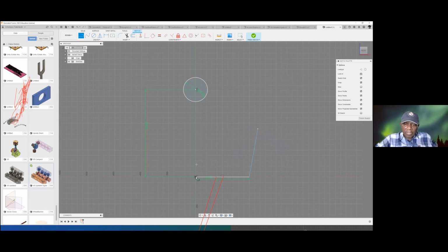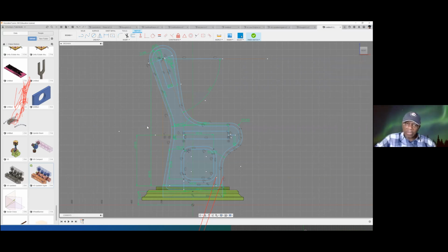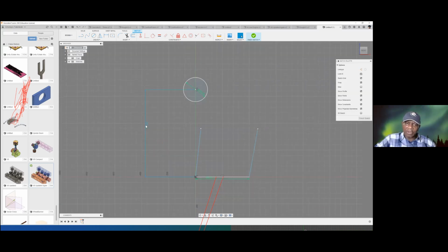Also take this one, pick it here. So I can take, I want a line from here that is tangent. I want a line from here that is tangent to, but this 650 looks so small. Let me just take a look at what I had before. Is this 650? No, it's not 650, it's 850. No wonder, because it was just looking too short. Okay, so if it is 850, not 650, all I do is to go and edit this. 850. Okay, that looks better.